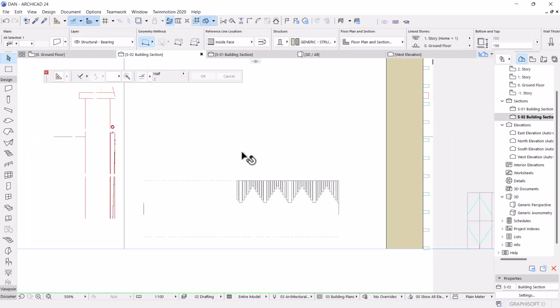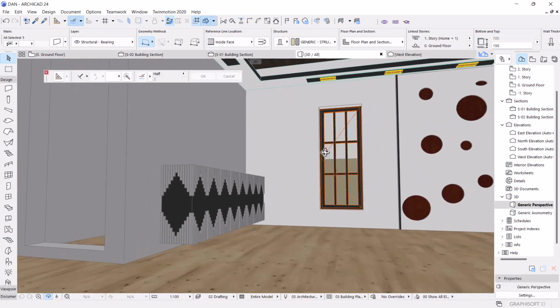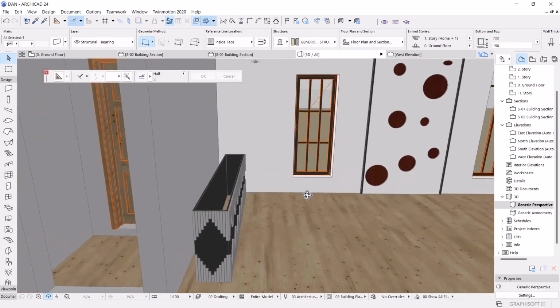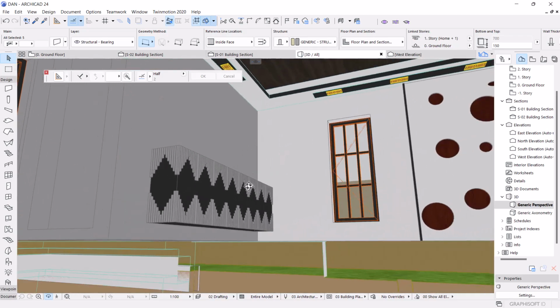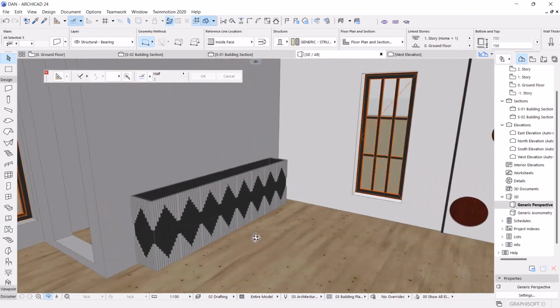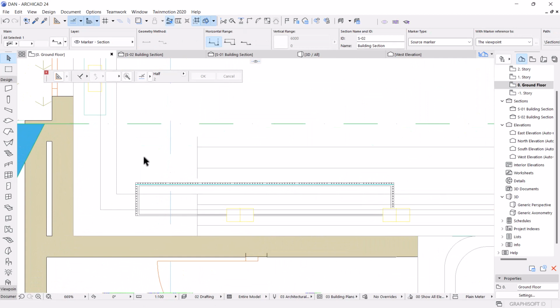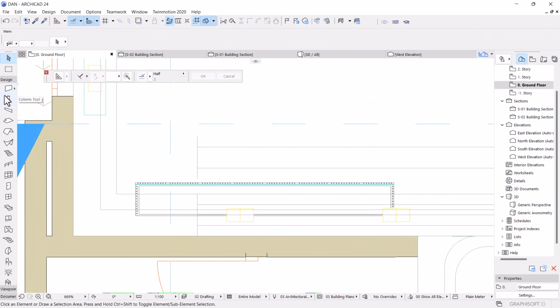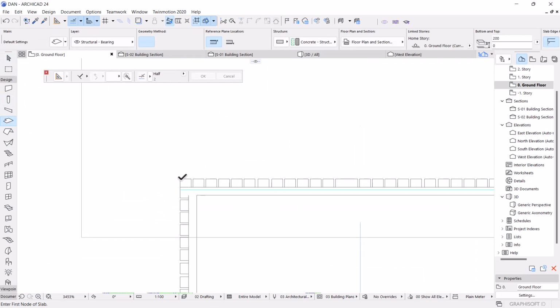Why is this one still here? Yeah, so far that's what we have. We have to close the top as well, so the top we're going to close with a slab. Let me draw the slab while we are still there. So we click on the slab tool, and we want to draw, we can use this method.